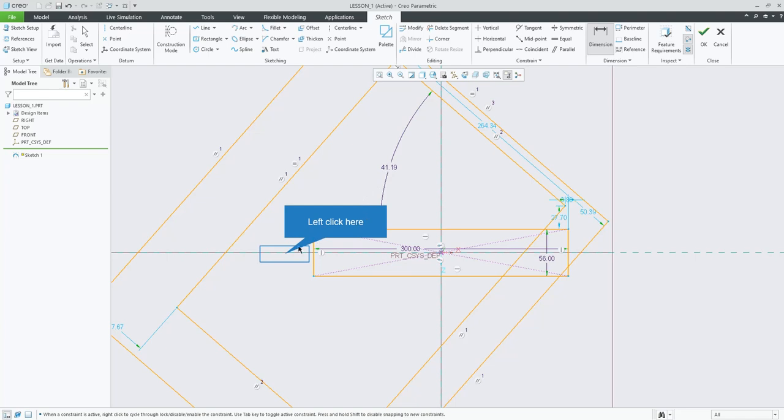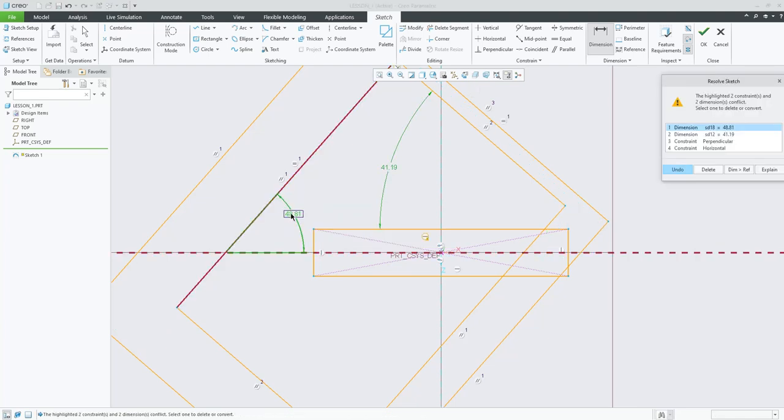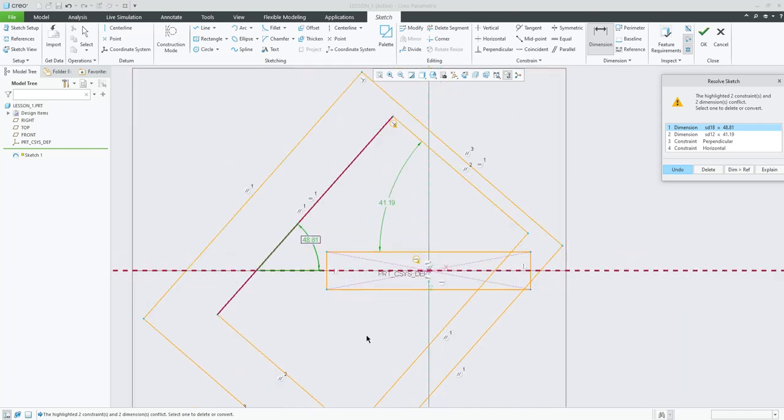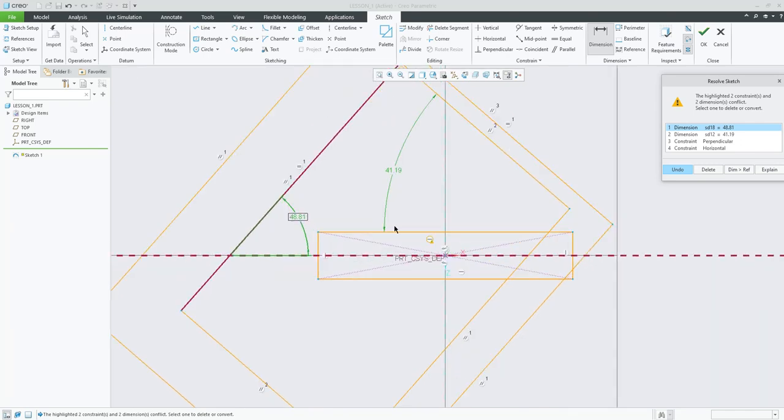So there was an angle right here that was a blue dimension for constraining this without our interference. Now that we've interfered, we've added a dimension, it deleted that reference, that dimension, and so when I try to create one, it's saying it's overdefined. So we have too many references that determine the angle of this part.